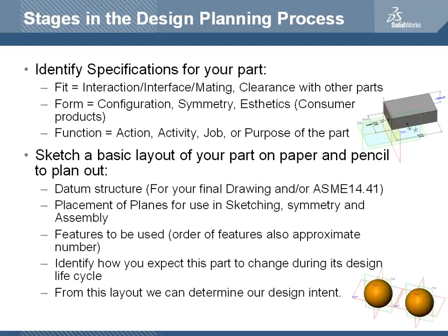Other considerations here would be clearance with other parts, or maybe from a real-world standpoint, can this part be installed easily, or if it's a high-wear part, can I replace it or maintain it easily? This kind of ties in with clearance with other parts. If we're working in tight quarters, will my part wind up occupying the space that was set aside for another part?